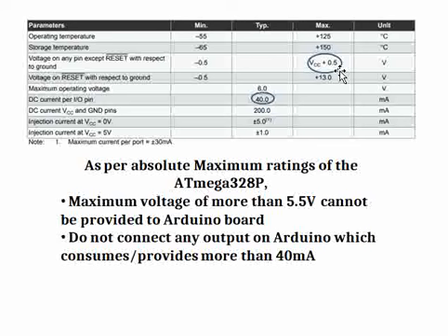And then we connect a number of circuits to the Arduino, right? For example, we can drive an LED, we can control a relay. There are many things we do, connect some pull-ups. So basically there are n number of functionalities outside. Sometimes because of the load that is connected, the Arduino board has to sink current, or it has to give out current.